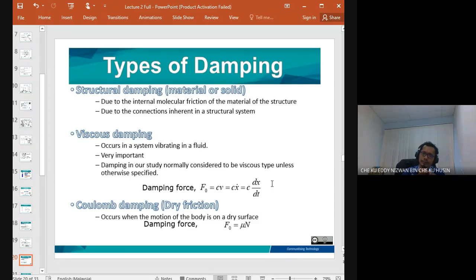The most important thing is that for a more luxurious car, they separate the system: the body is one mass, and the tire is another system. So the movement is only on the tire, and the force from the deflection of the tire isn't transmitted to the car body, due to the damping. It is very absorbed, and the end of the absorber has very minimal deflection, so the car body only receives minimal motion in the vertical direction. That's why viscous damping is mostly used to control vibration.